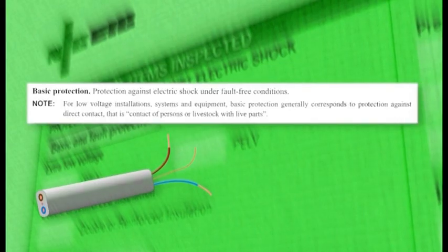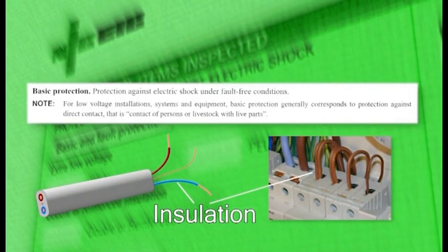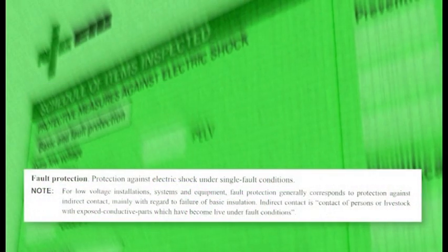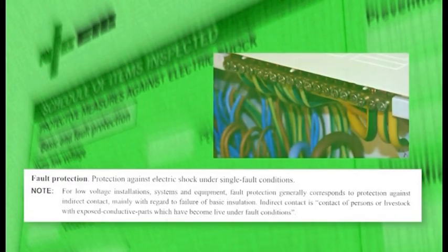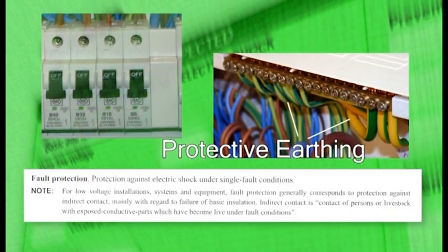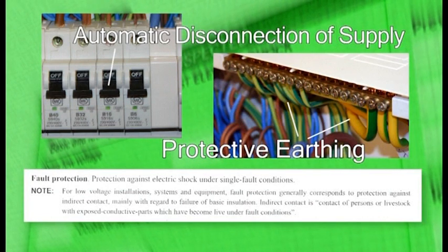In its simplest form, basic protection is insulation which is applied to live parts, so preventing contact with live conductors. And fault protection will most commonly involve, for example, protective earthing and a means of automatic disconnection of the supply for single fault conditions which could cause exposed conductive parts to become live.